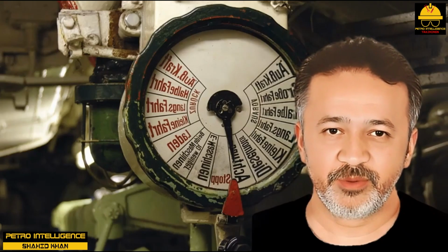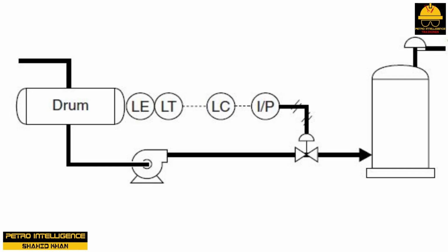Level control loop. A typical level control system uses a primary element sensing device, direct or indirect, level transmitter, controller, transducer, and control valve. Level control loops use floats, displacers, or differential pressure transmitters. This picture uses a DP cell to detect level changes.